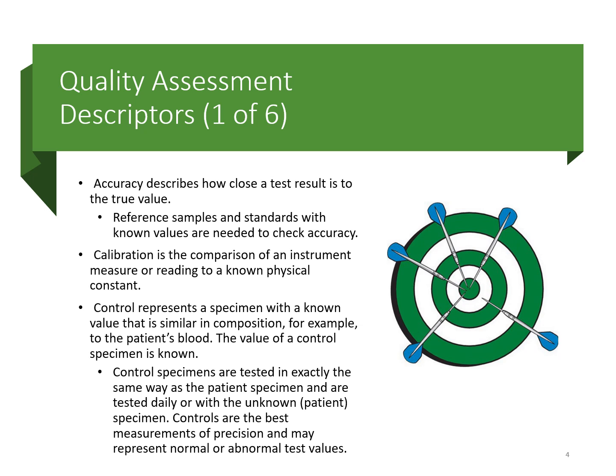And so when we're looking at calibration, this is going to be your constant. Anytime that you run anything on this machine for this value, this is what it should be. Calibration standards are sent out and have to be performed on a machine to set the center point value for that particular analyte. And then your control is going to be part of your daily routine to assess whether or not you're hitting that point every time.